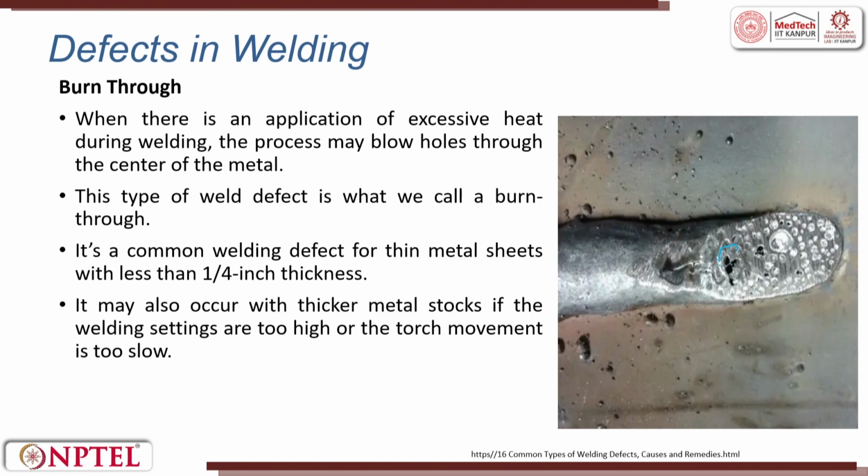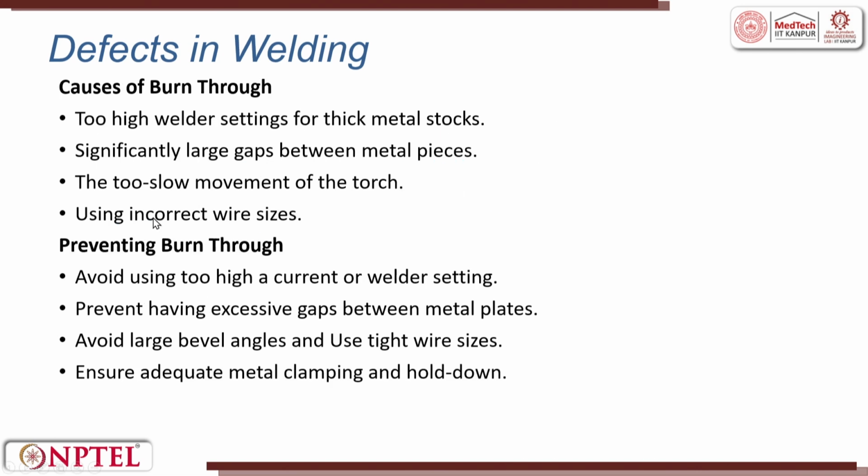So, these are burn through. With the application of excessive heat during welding, the process may blow holes. Many blowholes through the center of the metal can happen because of excessive heat. There can be vaporization and the metal viscosity is very low, so it spreads very fast. The process may blow holes through the center of the weld. This type of weld defect is called burn through. Again, the cause and the prevention. Friends, I am not going deeper into it because these are all for self-learning. I would request you to go through them.